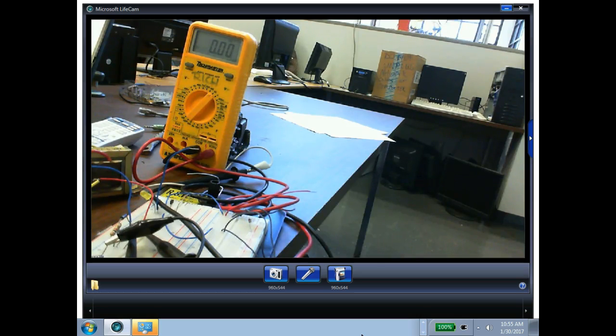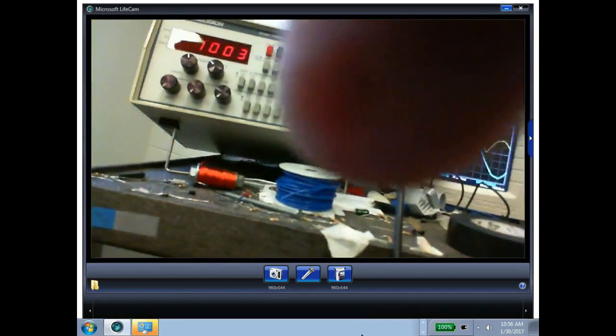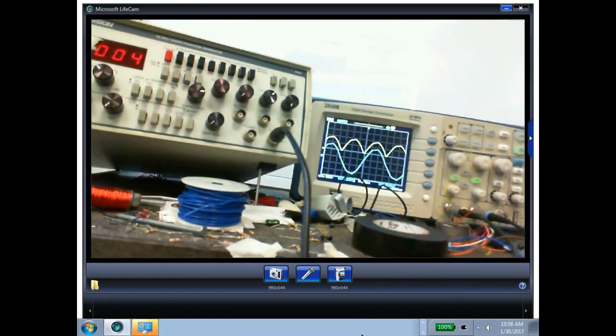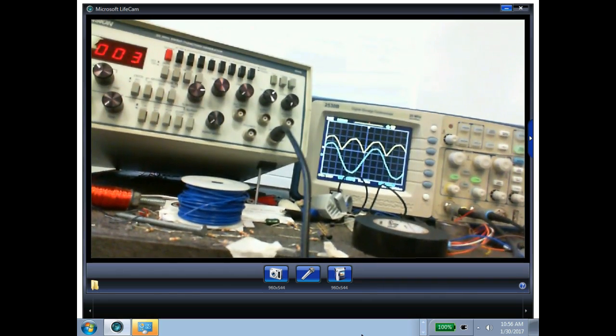Battery chargers don't care. You ain't gonna see a battery charger with a filter on it because the battery itself acts like a filter. So if you got a battery charger and you put it on AC and you put a scope across it, you're gonna see this stuff right here. It's usually full wave. There's a transformer in there. That's why they're a little heavy. There'll be a transformer in there, and then you'll see pulsating DC. Now, if you hook it up to your car battery, it's going to smooth it out because your car battery acts like a filter. This is pretty neat.